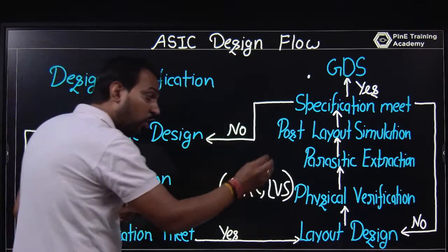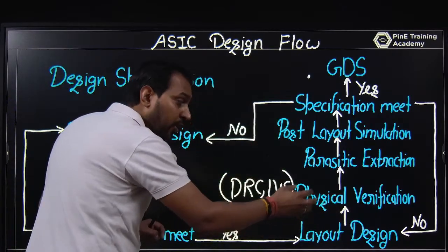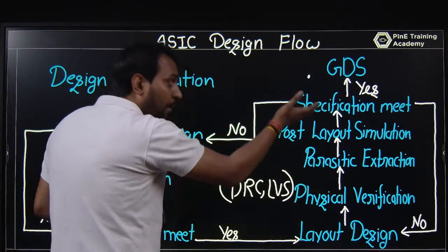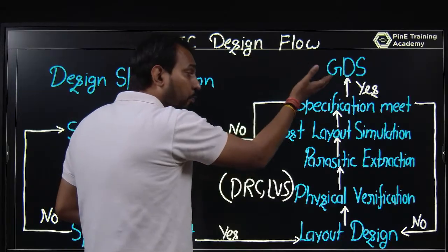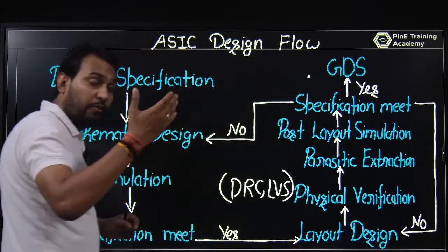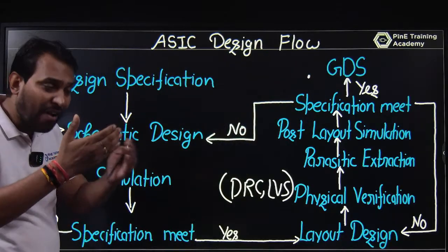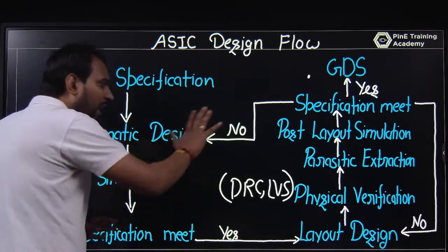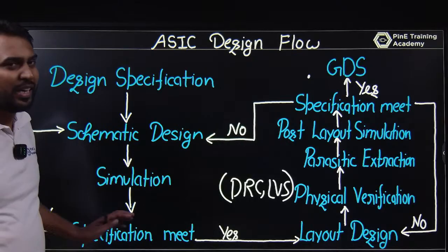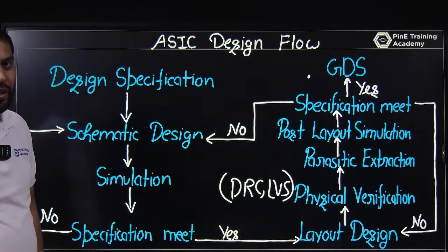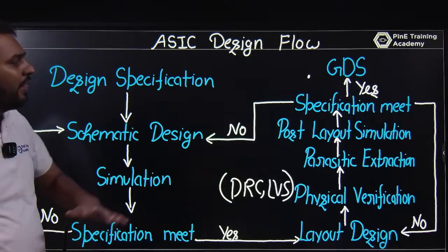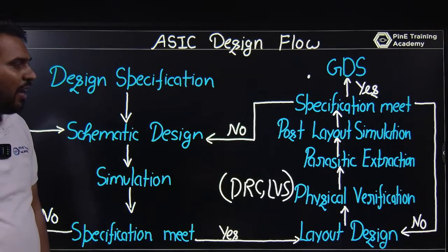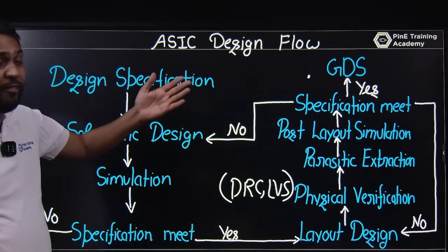Similarly, the layout should be as good, so that your layout and schematic match. After the post layout simulation, the post layout result will match or have a maximum difference of 5 to 10% from the schematic circuit simulation. Then we will send that GDS file, which is a binary file.